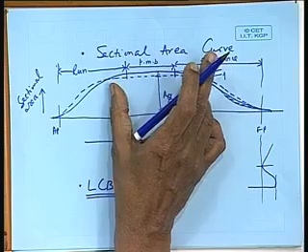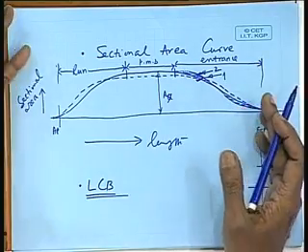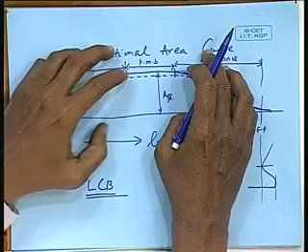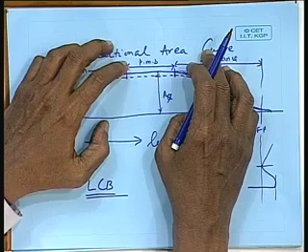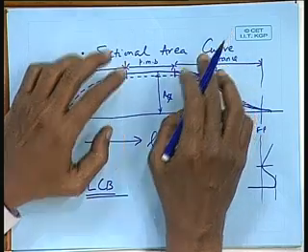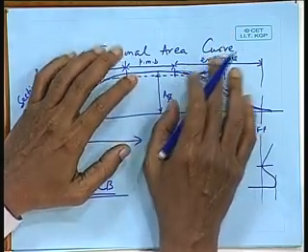Which is better? You see, now my parallel middle body has increased, good from the production point of view. I have made the bilge radius large, thinking that the bilge flow will be smoother, but in the process I have made my shoulders very prominent. And if I have large shoulders, I know I will get into trouble.